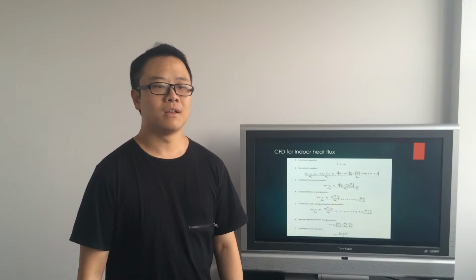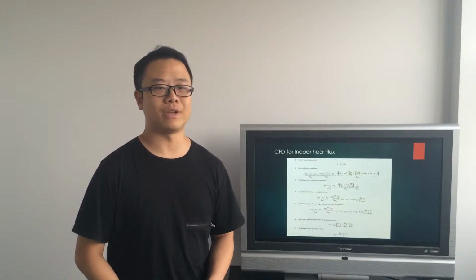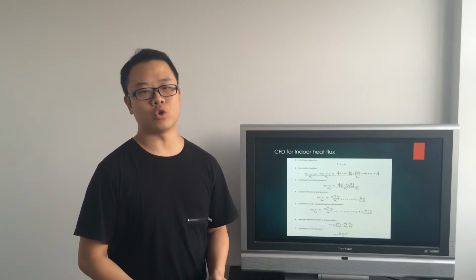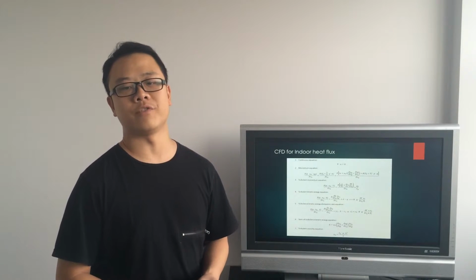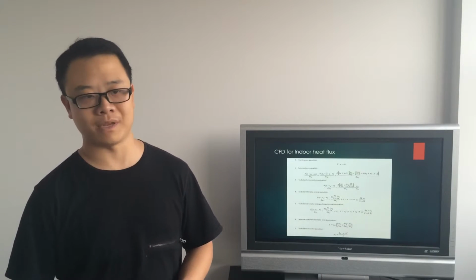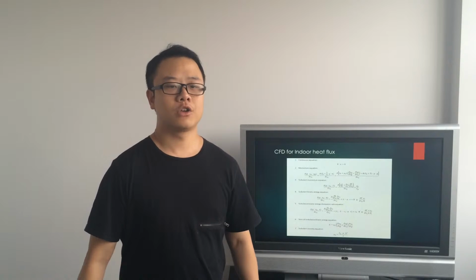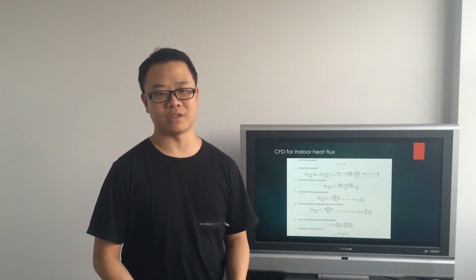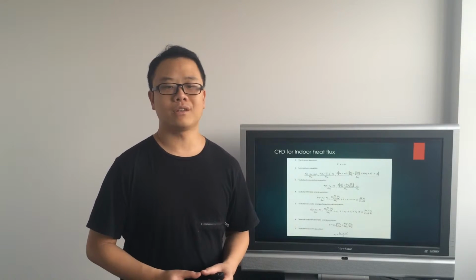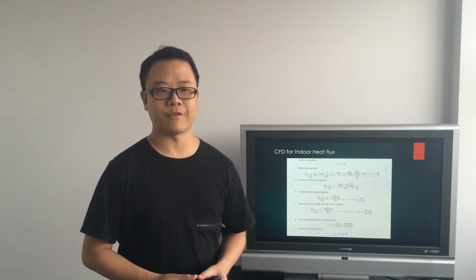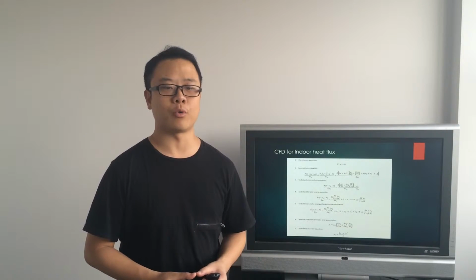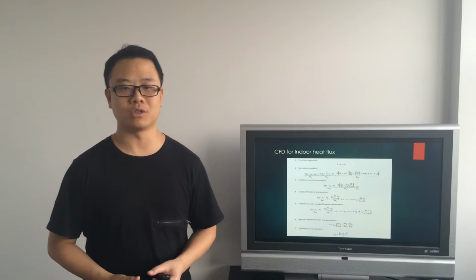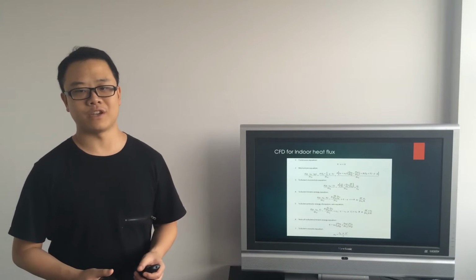Epsilon denotes the dissipation rate of the turbulence. Rho represents the current density of the fluid. Fp is the pressure mean value in the time domain. Qt represents the heat source intensity, where T is the current temperature in the fluid field. T0 represents the operating temperature. B denotes the thermal expansion coefficient.